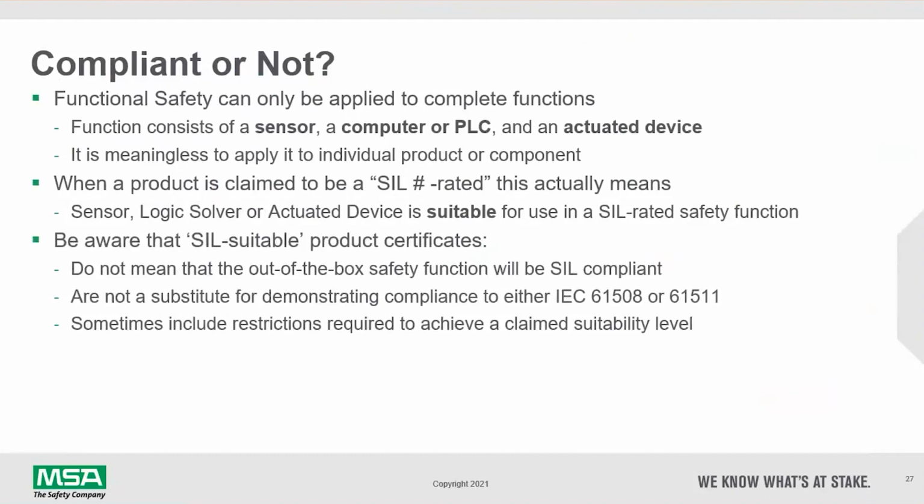And also be aware that some SIL suitability certificates for products may have some restrictions or caveats. So again, be aware, out of the box doesn't mean it's compliant to any particular level. It is not a substitute for demonstrating compliance to either 61508 or 61511.